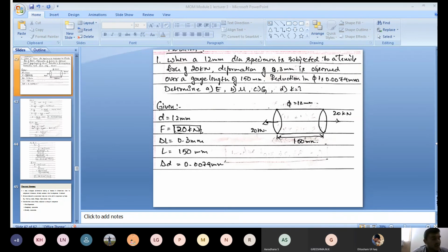Next, we go for calculating bulk modulus. How do we calculate bulk modulus? We know Young's modulus, we know the Poisson ratio, and we know the relation between Young's modulus and bulk modulus. E is equal to 3 times K, into (1 minus 2 times nu or mu). Again, whatever bulk modulus value you get, that should be less than Young's modulus. Yes, we will tell the answer for the last one.